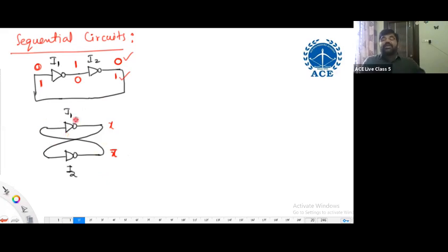But if I give it, it can remember, but where should I give that input data? It is not possible in this circuit. That is the reason we need to have input terminals. So memory element means not only remembering, it must be having other functions also. What is that? It must be allowing us to modify the data to 0. It must be allowing us to modify data to 1. Irrespective of existing data, I must be in a position to feed my own data, which I would like to store in this memory element. So memory element means not only remembering.